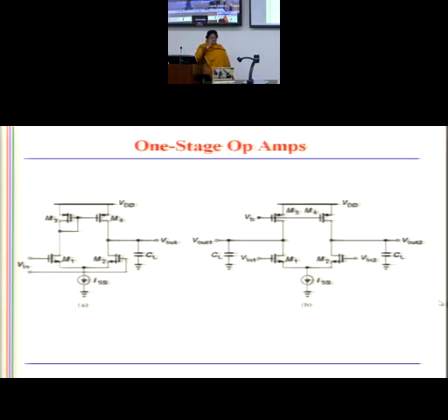You know how to analyze these circuits. Analysis in common mode, analysis in difference mode, analysis with a current mirror as a load. The behavior of the source coupled node, the behavior of the output node, the behavior of the mirror node. Swing, how to calculate swing, how to calculate ICMR, how to calculate OCMR. And then the locations of poles and zeros.